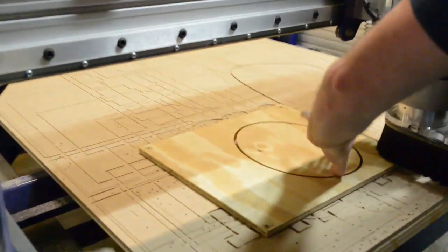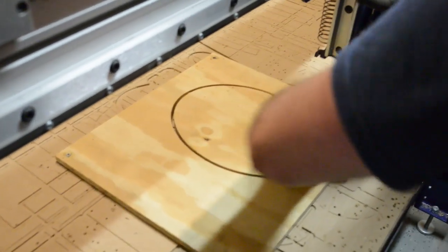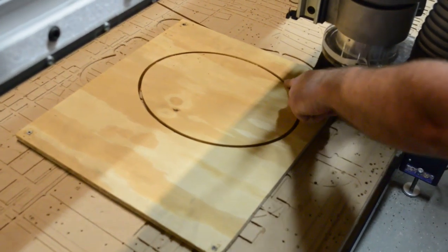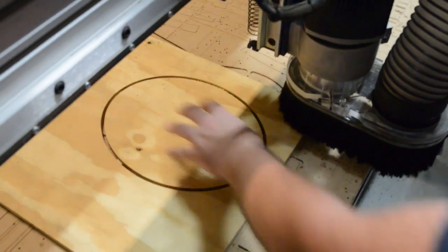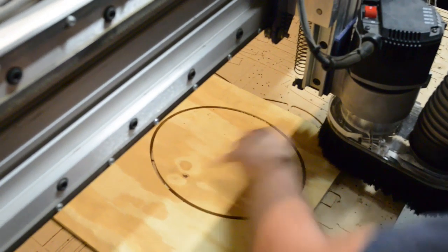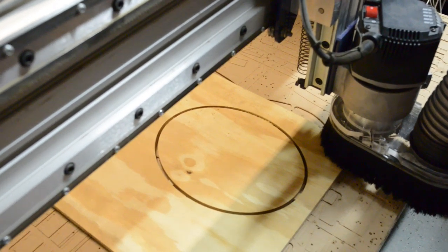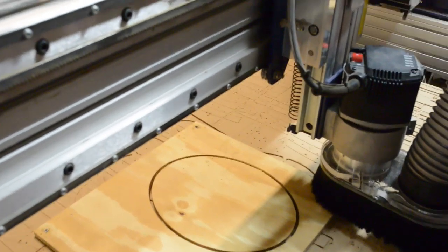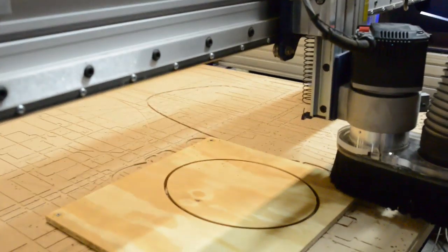It's cut all the way through, but our tabs are now holding this in really well. If you look through there, you can see the MDF spoil board shining through. But those 4 tabs really got it in there. So it's okay for me to now go and do my engraving path, knowing that that's in there pretty well.